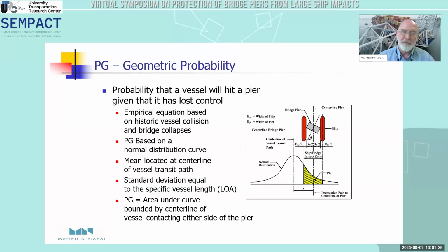The 1 in 50,000 where the rogue ship has gone aberrant, that vessel could be as far as 3 times LOA from the navigation channel, or 2 times LOA. So while AIS data is very informational and an important resource, in my opinion, it does not tell you where the rogue aberrant ship goes. And the AASHTO code and its 3 LOA feature is to say, where might the rogue ship be located?